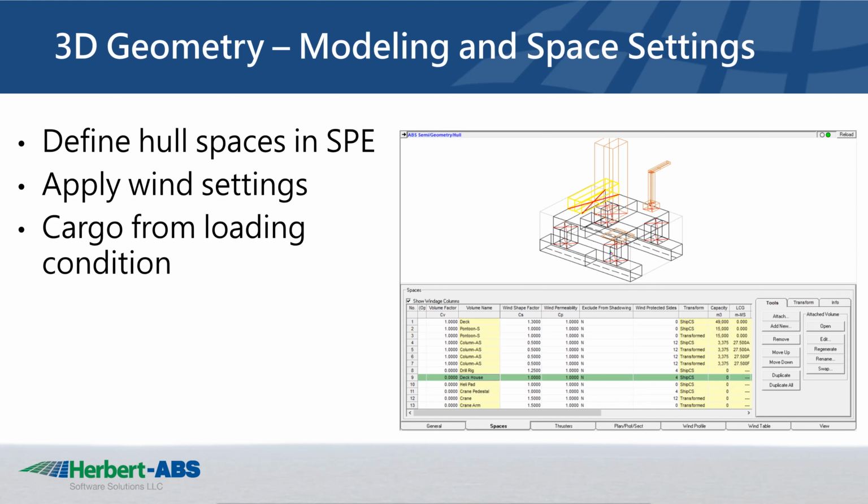Next is the wind permeability, which is another multiplier in the overturning moment calculation. This is treated more as a design factor to consider how the actual part is built up. So say, for instance, on our crane arm, if this is open trussing, the wind is more able to pass through this rather than if it were a solid beam. The permeability can be applied to reduce the effects of the overturning moment because of how a piece is designed.